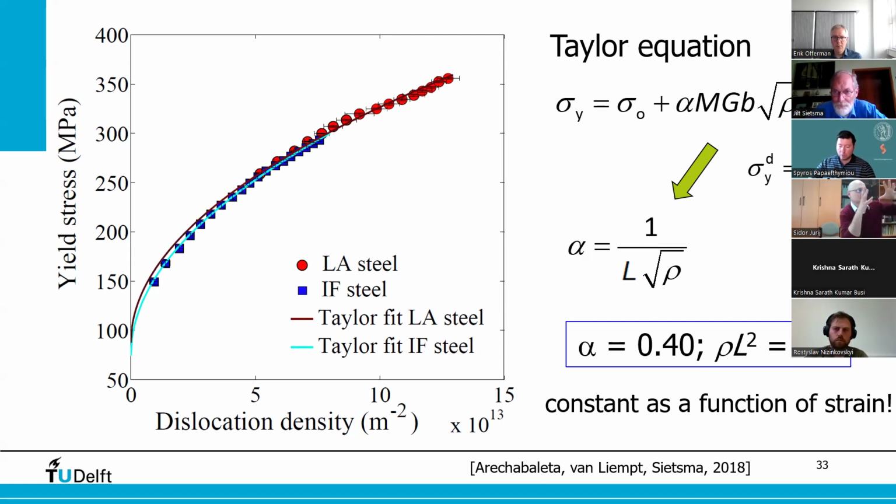But it also depends on the way the cell walls are built up, because the density will be much higher in the walls, so the segment length will be smaller there than in the interior. So the overall dislocation density will be low, because you have dislocation-poor regions, but where there are dislocations, the segment lengths will be relatively small, I think. Something like that. Yeah, okay, thank you.